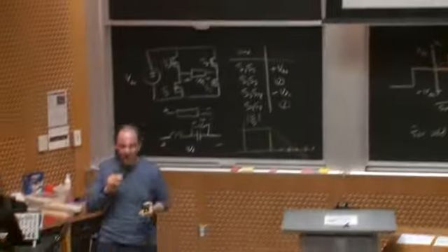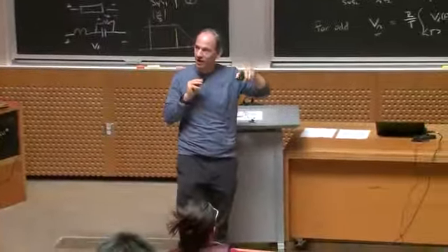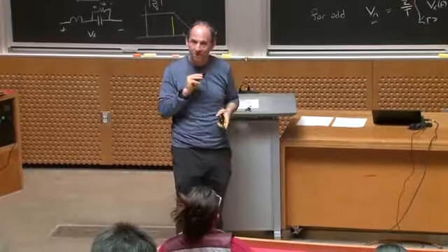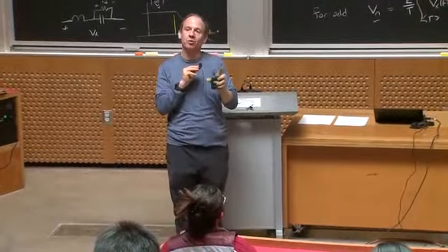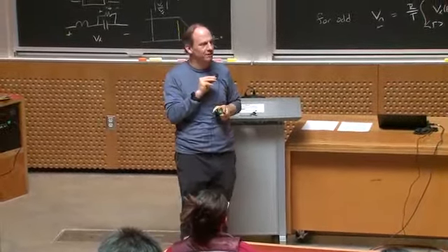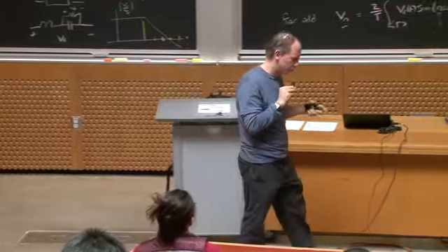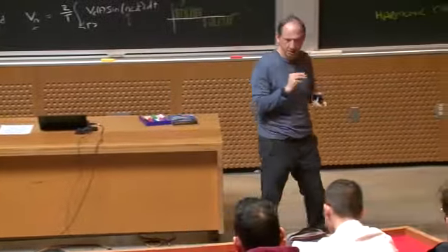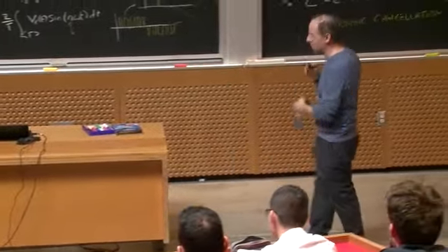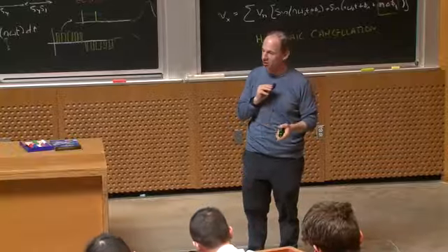Thanks. So what we've seen today is harmonic elimination, where we introduce extra pulses carefully timed. We've also seen harmonic cancellation, where we take multiple waveforms, shift them and add them up to murder the harmonics we don't like. Those can both be used together. What we'll start seeing next time is other ways we can do this harmonic cancellation or elimination game, with more sophisticated circuits.